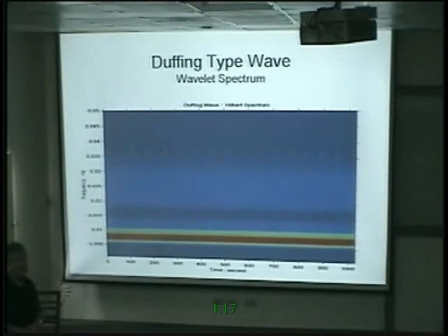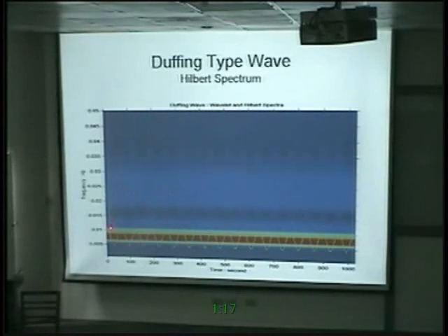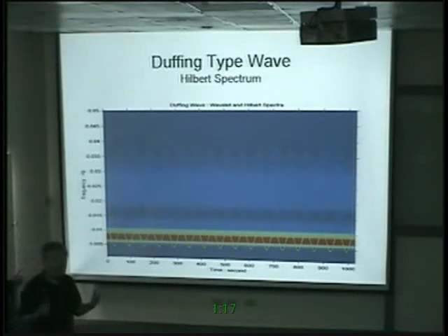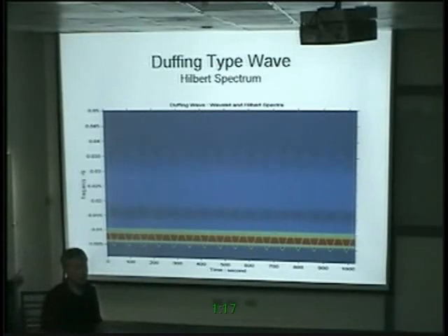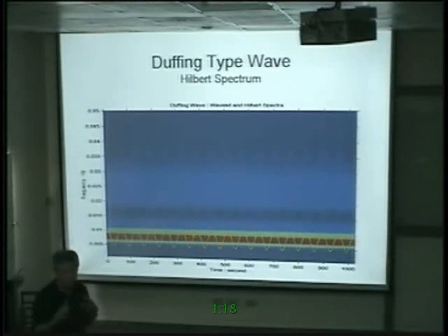Even though this is not a Fourier transformation, we can use Fourier transformation, use a spectrogram. We will get sine omega, sine 2 omega, sine 3 omega. Now, what Hilbert will give you is actually a sinusoidal function. Hilbert will say, listen, there's no constant frequency. The frequency keeps changing. How does it change? It changes up and down, up and down. For each period, I actually change twice. And that's exactly what the mathematical model says.